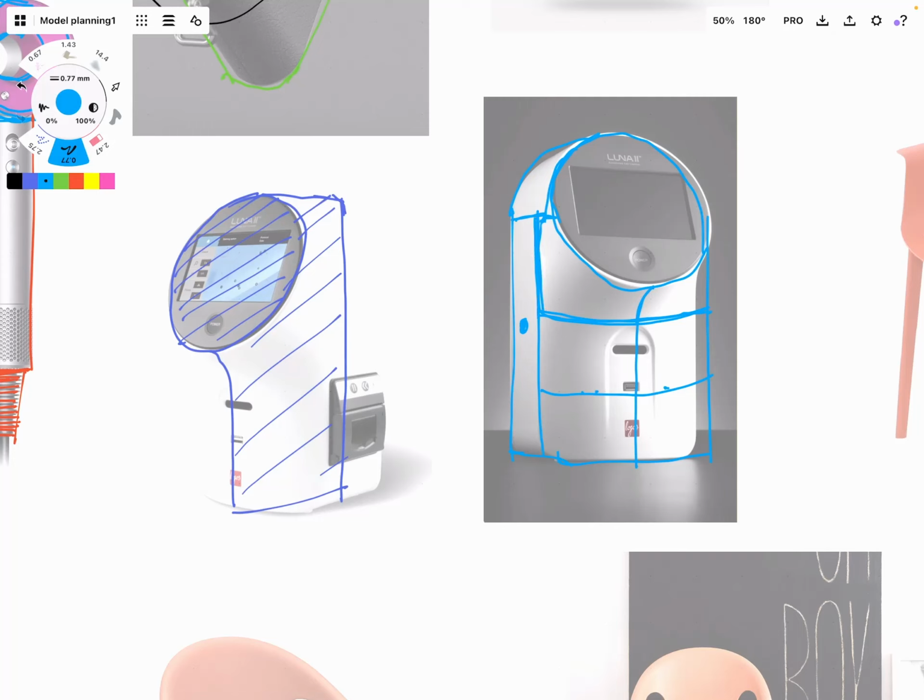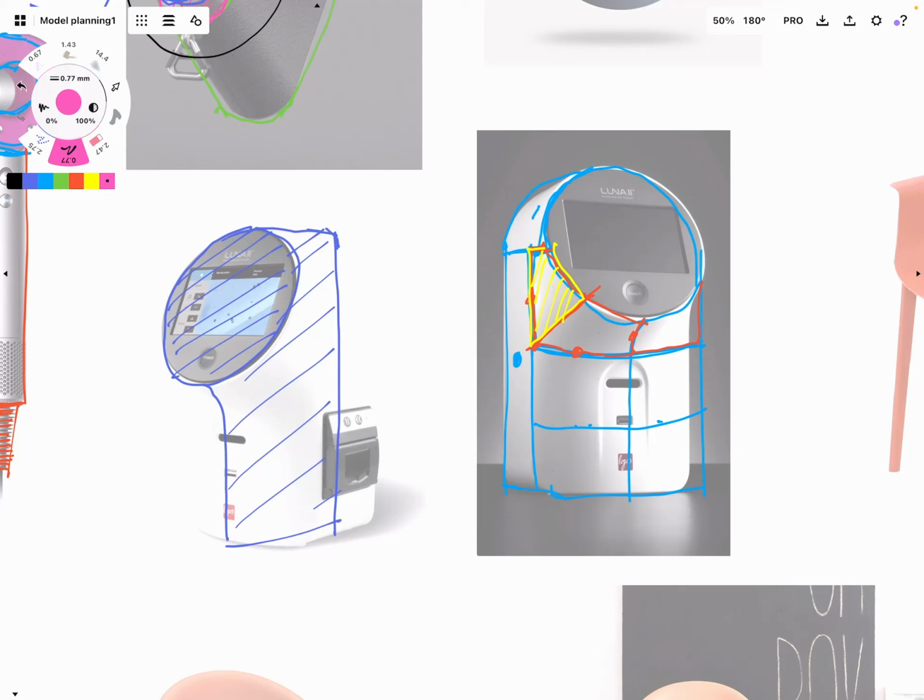So if that's our crease there, and the crease stops, you'd want to have another surface here, so we'll change colour. So we've got this patch here, this hole we need to fill, which has 1, 2, 3, 4, 5 boundaries on it. So I'd probably run another control sketch through here, a section, and then you'd build one surface there, which has got 1, 2, 3, 4 boundaries on it, and then this one here, 1, 2, 3, 4 boundaries on it.